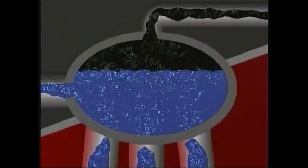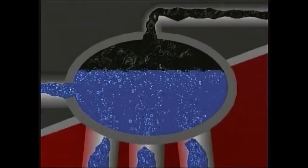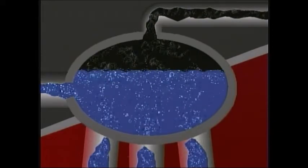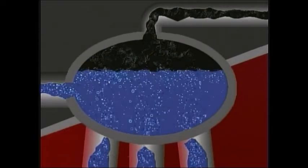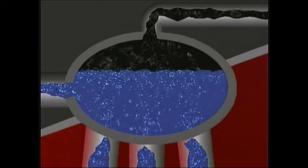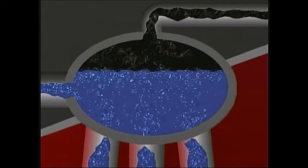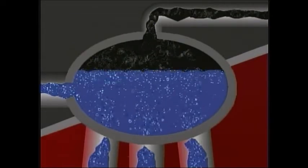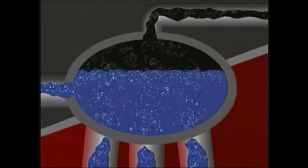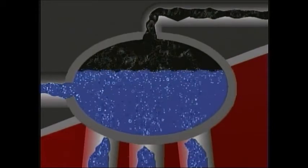In the steam drum of a boiler, the water exists in two states, both liquid and vapor, and both the liquid and vapor have the same temperature. But the vapor, or steam, contains much more heat than the liquid. This is because the steam contains not only sensible heat, but also the latent heat which was transferred to it to cause the phase change from liquid to vapor.